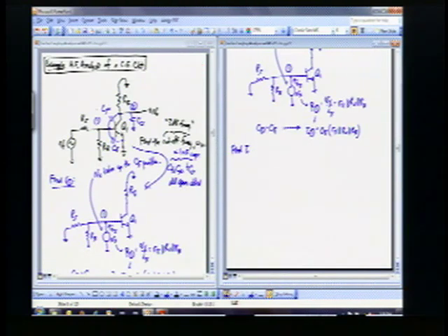Okay? And so I'm going to call that T mu naught. Because C mu, right, it's not associated with any node. It's not associated with node 1 or node 2. So I can't say that it's just the capacitance associated with that node, and then I can't use a driving point resistance that's just associated with that node. I actually have to go in and solve the following circuit.